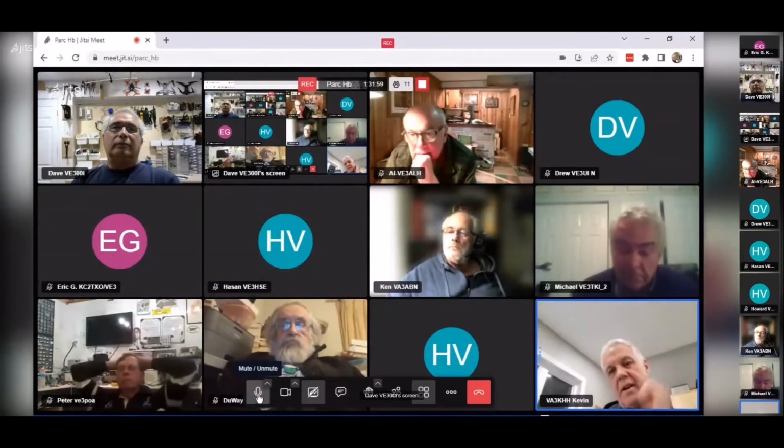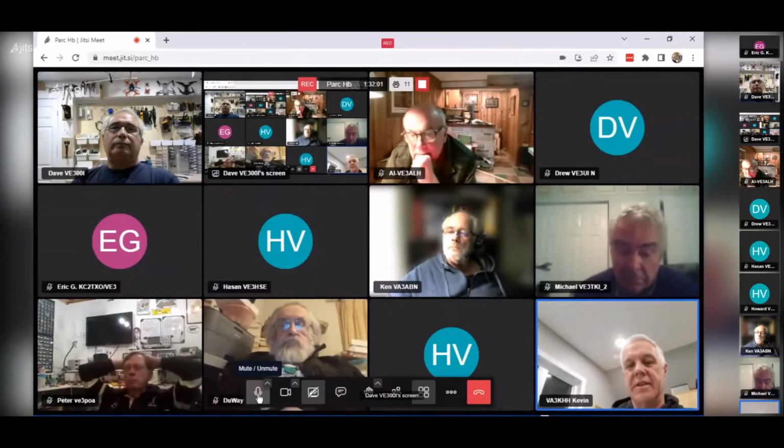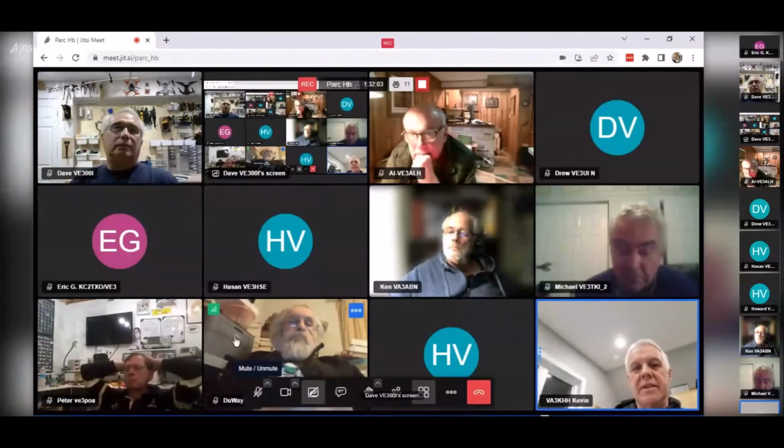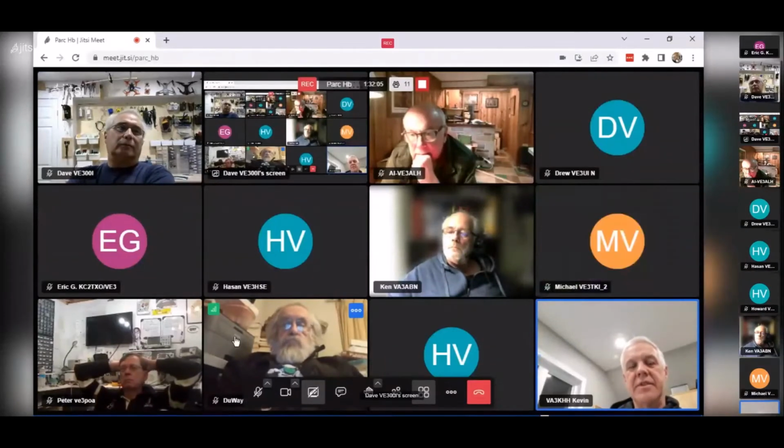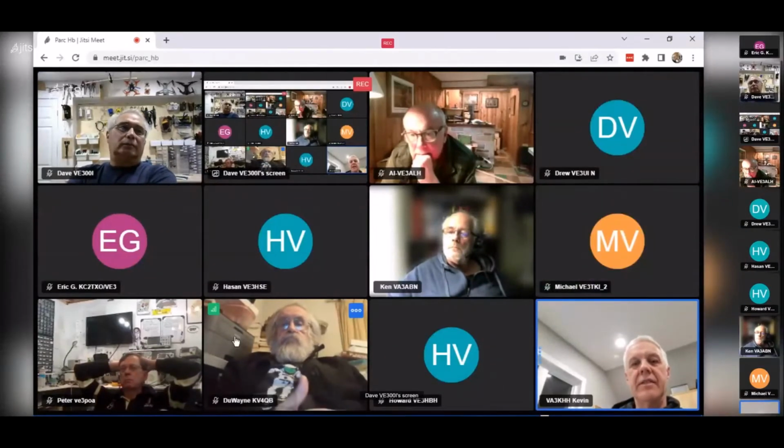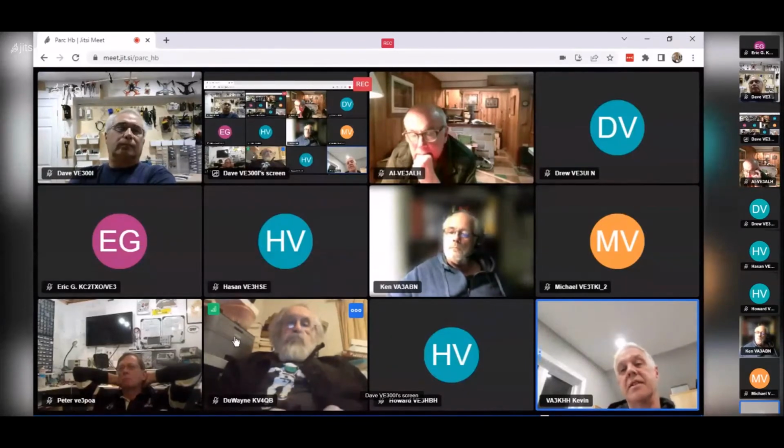Just for this, the speed and torque on the stepper and the servo. Steppers normally, you can get a lot of torque at low speeds, but it's a nonlinear torque curve too. The higher you go, the less torque you can get out of it. Whereas a servo, you'll get constant torque over the entire speed range. And a servo can regulate position just as well as a stepper because it's got an internal torque loop, right? So if it doesn't get where it needs to go, it applies all the torque it needs to get there.